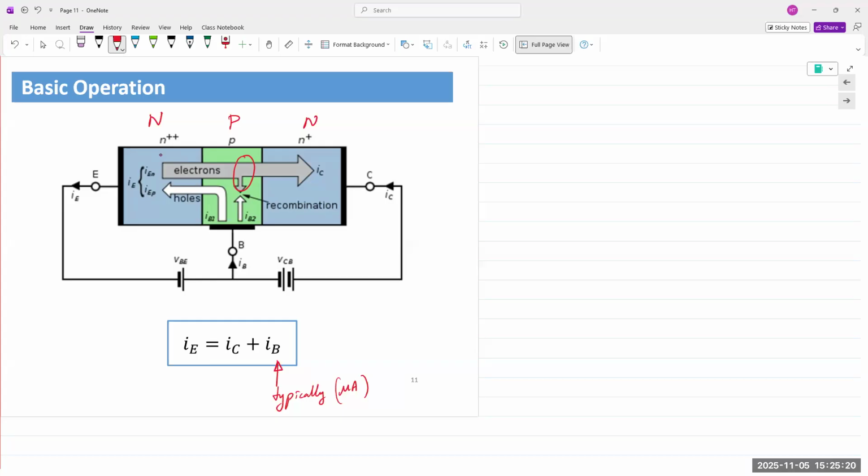But there's a small amount of reverse current that flows through because of the minority carriers that are crossing the junction. In this case, it's the exact same effect. The only difference is the minority carriers, which are electrons, are not from the P-type material, but they have come over from the emitter. They're hanging around with nothing to do, but because they're reverse biased, they're able to cross over and go into the collector region.